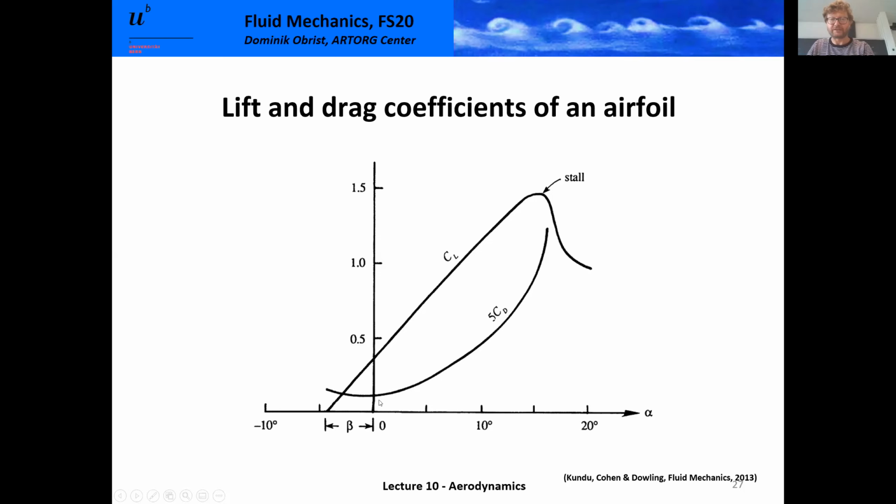The drag coefficient actually can be shown to increase quadratically with the angle of attack. Of course, potential flow theory doesn't do that. You need another kind of theory. But let's now just stick with the lift coefficient.